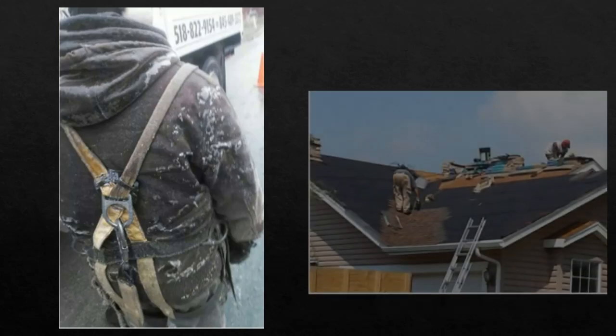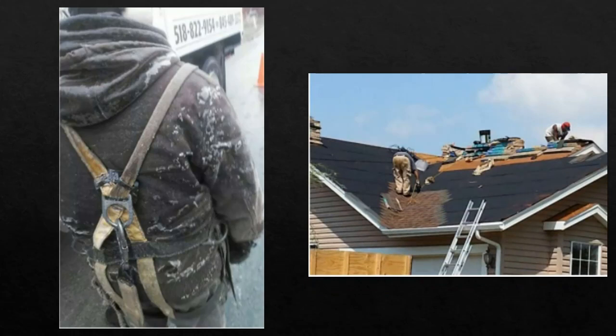This isn't ladders, but it's a fall protection system, a personal fall arrest system. It looks like it's been through some things. A harness and a lanyard and an anchorage point all need to be periodically inspected to ensure that when called upon, they can do what they need to do. And in this other picture, it doesn't look like we have 3 feet of overhang on that ladder that's gone up to the roof. So when these workers have to descend, it's not going to be easy for them to get on that ladder and to safely go down from it. Plus, it looks like the angle is a little bit more severe than the 1 in 4, or 4 to 1, that we normally like to see.